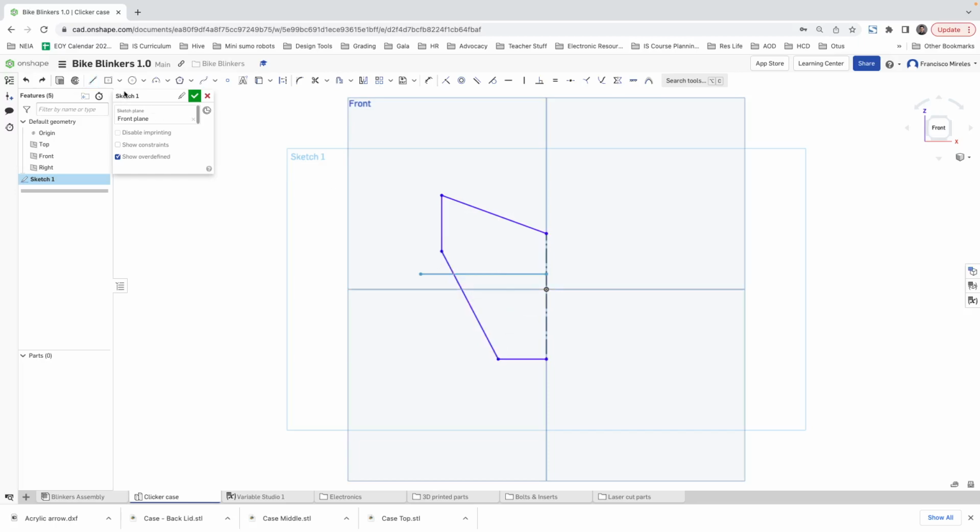All right, sorry. That little symbol that just appeared there is the one you're aiming for. If by any chance all your lines are not straight, that's fine. What you can do is just select this line and this line, this line and this line, and say perpendicular. This is the button. And then say, hey, this line and this line perpendicular. And with these three lines, which are going to be construction lines, we're going to simulate where the bottom would be, so we can get a reference of dimensions.